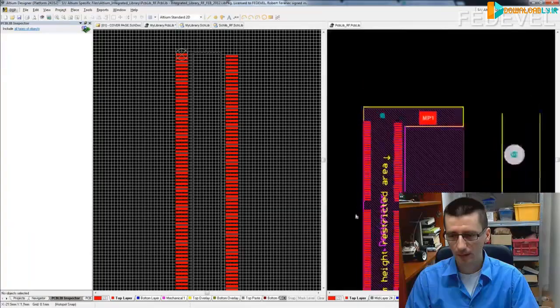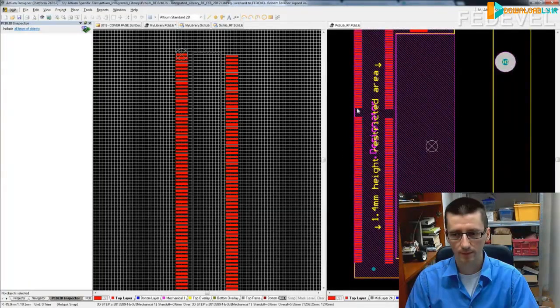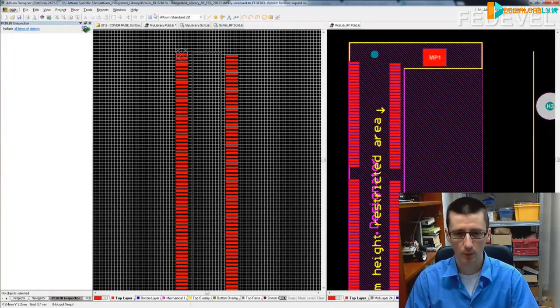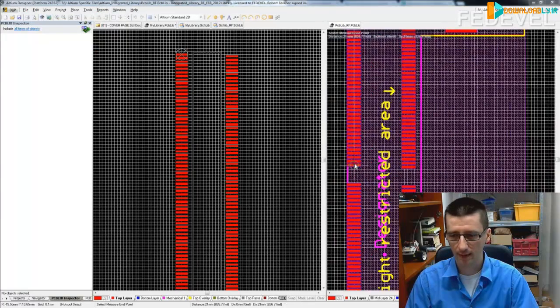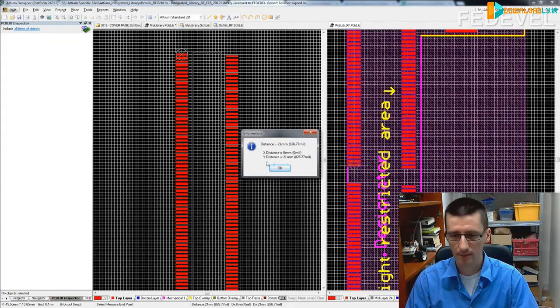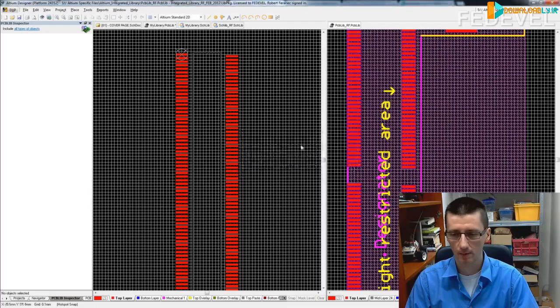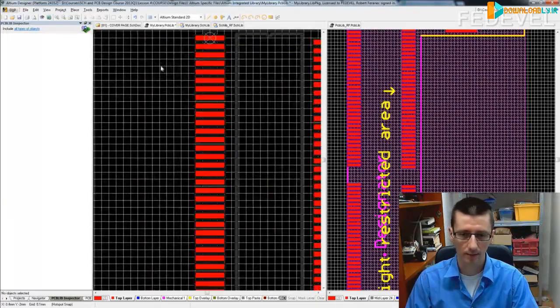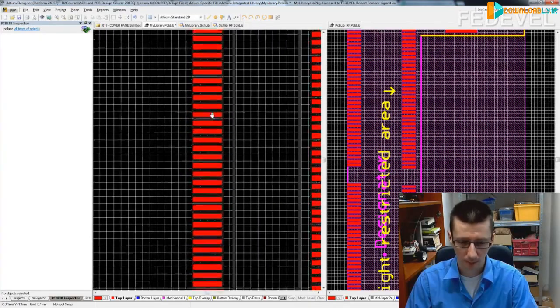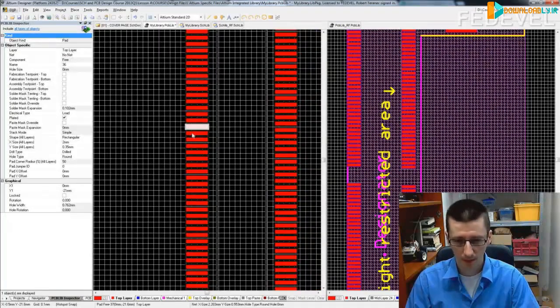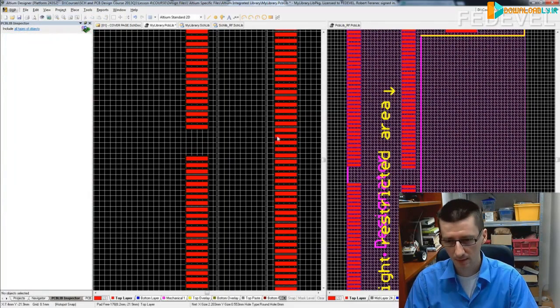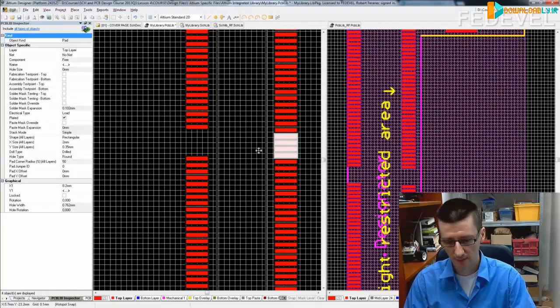And to make it look like our connector, we need to remove these few pins. I don't want to count them, I will just measure it. It's faster, so I will find the position of this path. It is 21 millimeters down. So I go to my component and I will be looking for the path placed in position -21. It is this one. So I need to remove 4 paths here. Press delete, hold shift down, press delete.